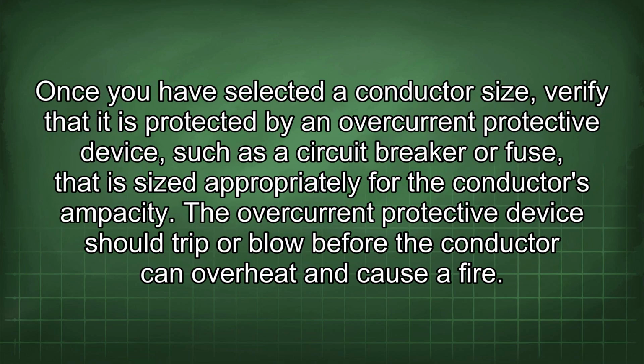Once you have selected a conductor size, verify that it is protected by an overcurrent protective device, such as a circuit breaker or fuse, that is sized appropriately for the conductor's ampacity. The overcurrent protective device should trip or blow before the conductor can overheat and cause a fire.